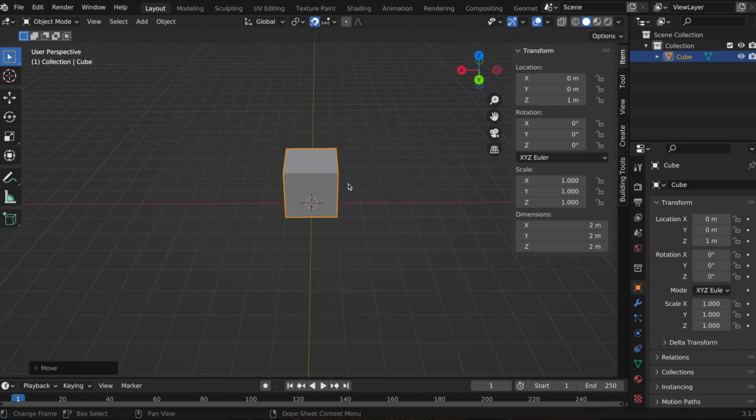So I'm gonna have a plot basically 2 by 1, and the 2 is on the axis. So I'm gonna make this one the longest. So each plot is 15 by 15, plus we gotta have 1.5 meter on the edges to allow space to walk or drive. So 15 and 15 is 30 meters, but minus 3, so that's 27. So I'm gonna make it 27.